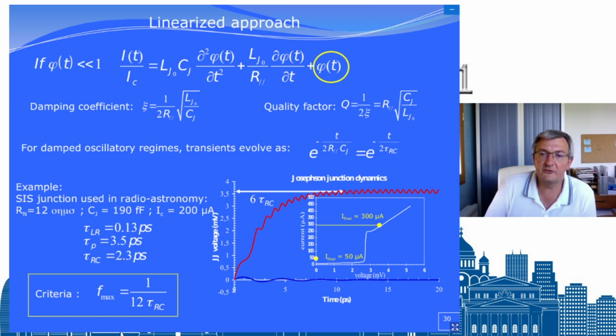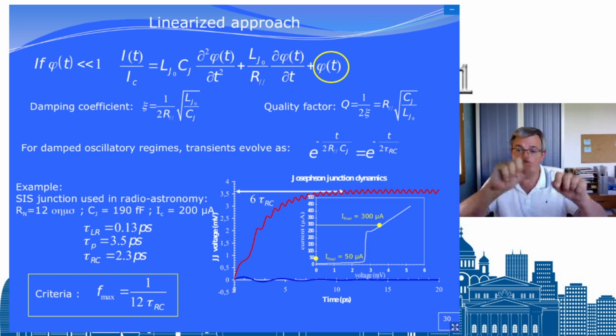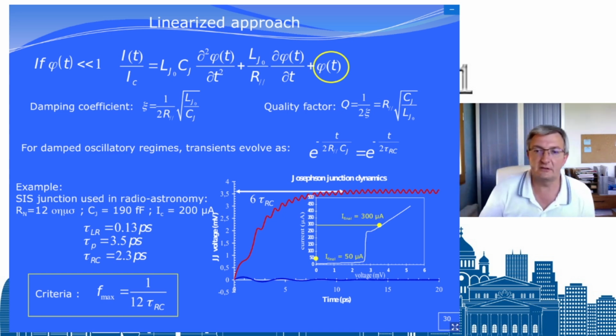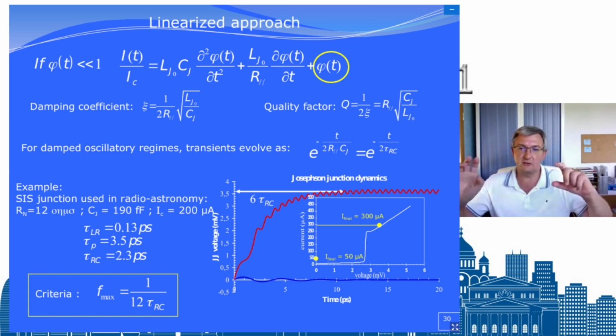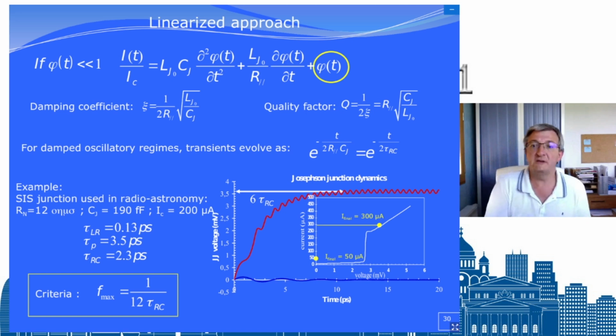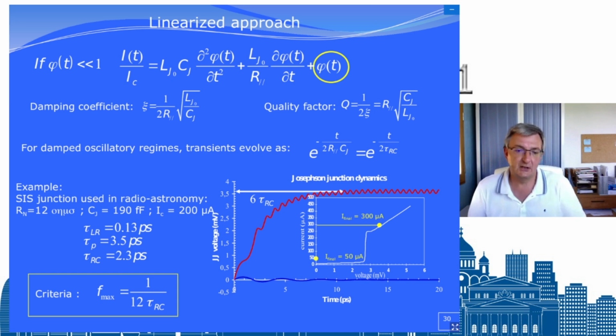And so there are different ways to do the transformer. If you do DC transformer, you really have your squid is just connected to a spiral, right? Both ends of the spiral to the squid, and you take another coil going to the electronics. It's a way to do it. So there is nothing. Both are really connected on a circuit, and they are closed circuit. But you can also do it in RF way, and then the spirals are not necessarily closed. They can be open, and then you have a resonance. You need to think only in terms of AC signals, and then it can do the same as well.